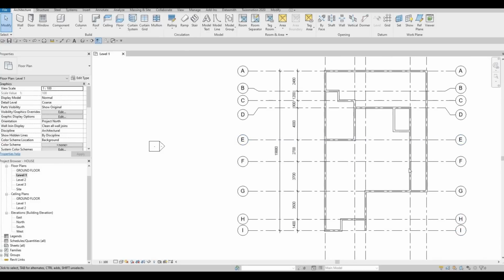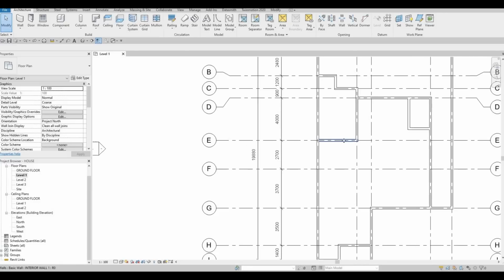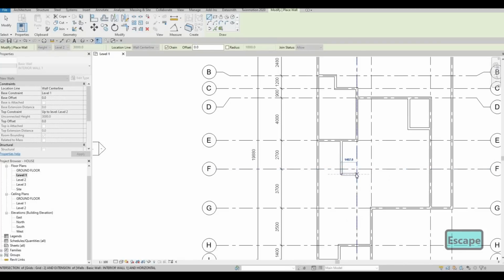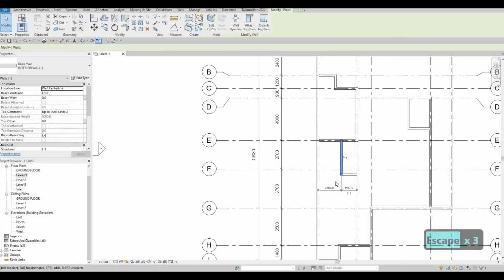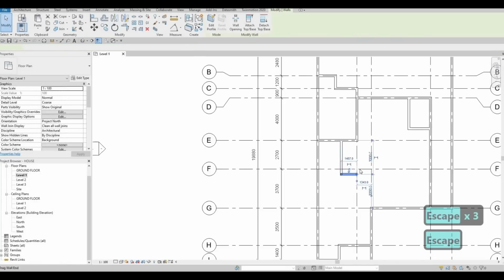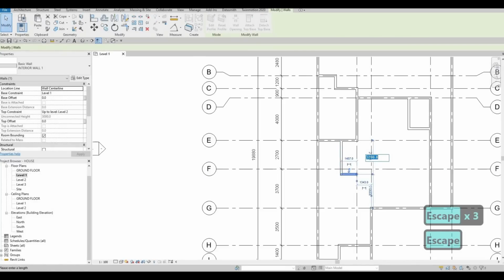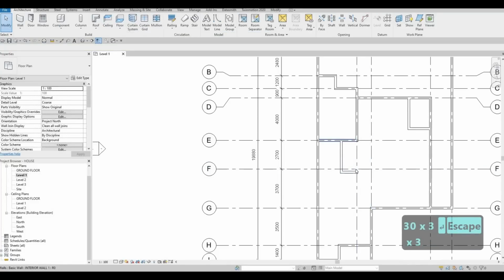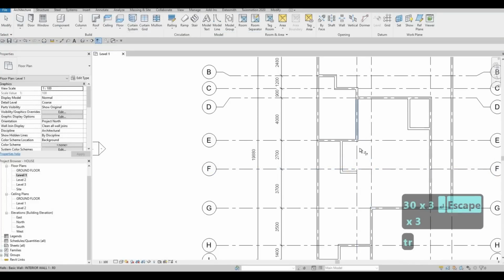So now that we have that, we could add in something right here, CS on the wall. So we already have that. That's easy for us to manipulate. We're going to add a wall right here. This will be around maybe 3000. So I'm going to make this one 3000. And then here, I'm going to close this off, TR.